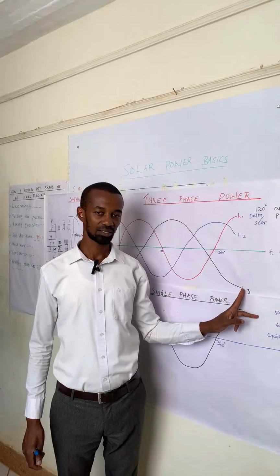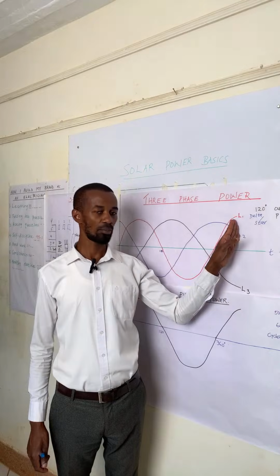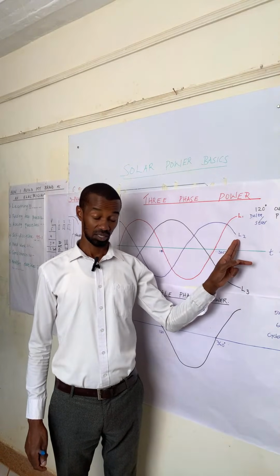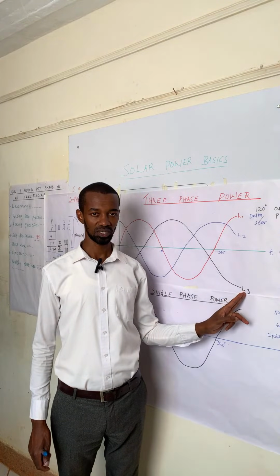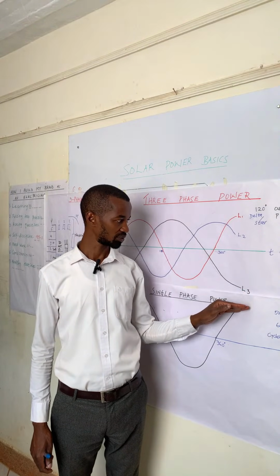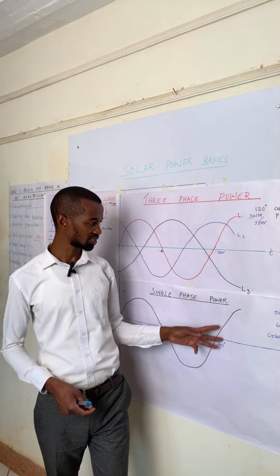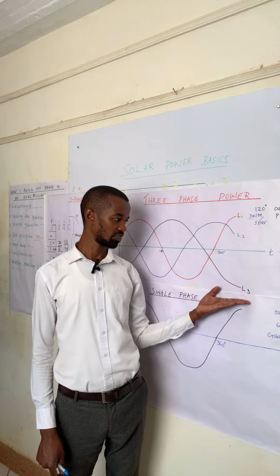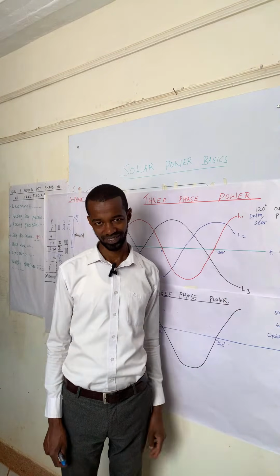Then the last but not least, what is the color? For our region, I know about the red phase, the yellow phase, which is at the middle, and then the blue phase, which is below. All right. If this distribution system is a three-phase at the secondary, then we have the neutral. And we have red, yellow, blue, and black.